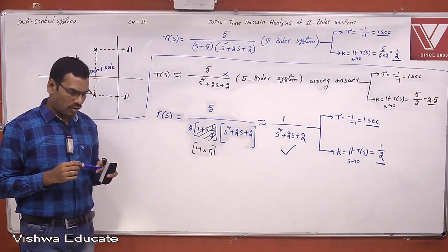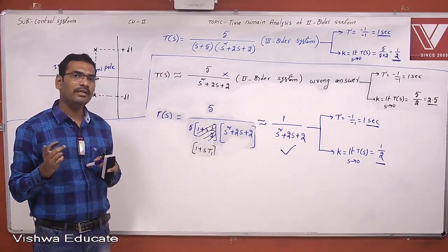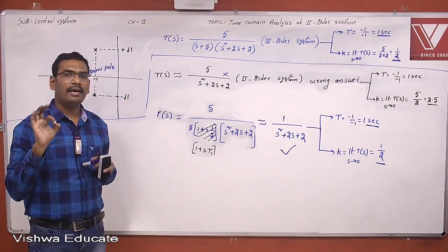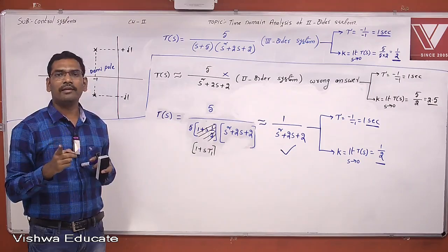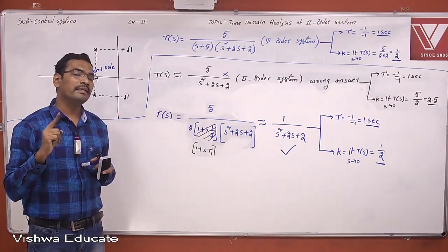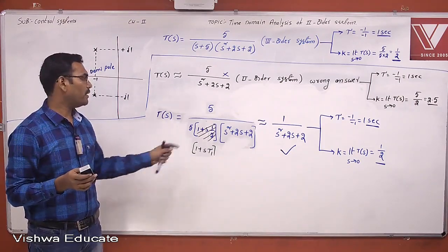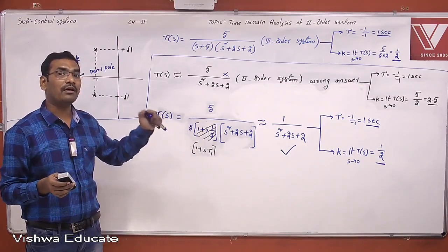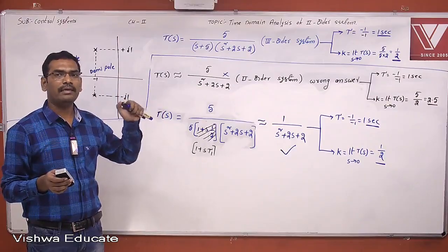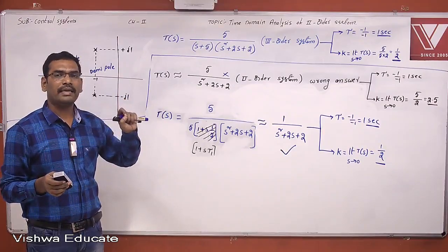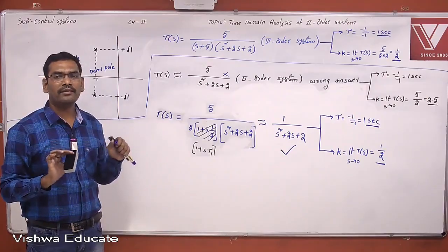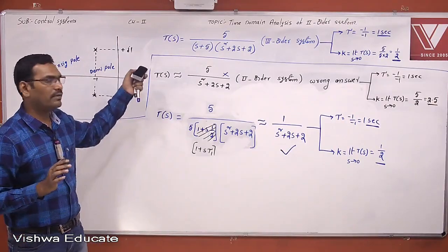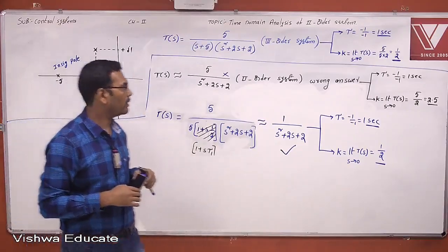Okay. So you converted a higher order system into a lower order system. By converting higher order to lower order, the insignificant pole is eliminated. Before you eliminate the insignificant pole, convert it into time constant form such that the system parameters will not be disturbed, will not be changed, will remain the same, such that the system behavior will not be disturbed. Okay. So without disturbing the system parameters, we convert higher order to lower order. Okay. Note down this.